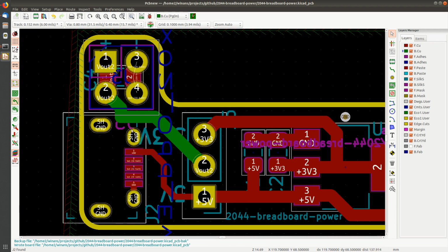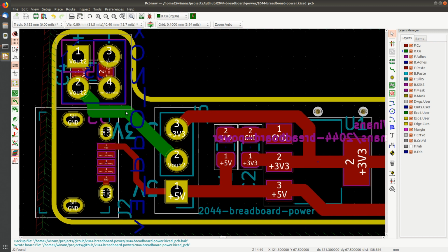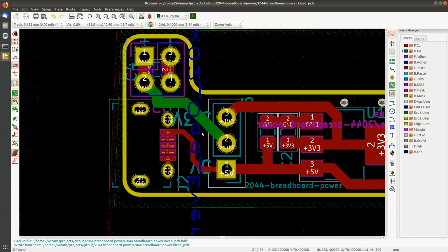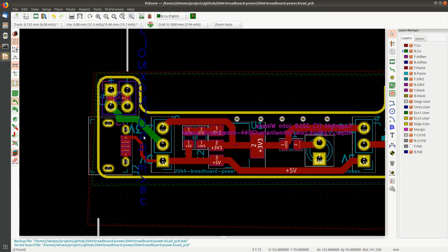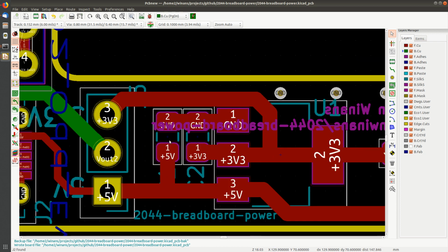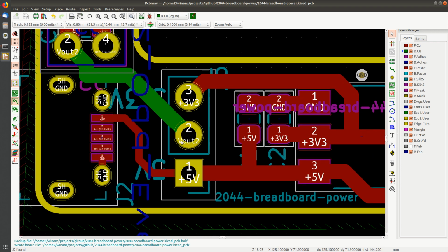That's okay though, because this pin's connecting the top copper as well as the bottom, as are both of these. So this on the top will be all copper up here. So it's good enough, especially for this simple design. Otherwise, you might need to put a lot of vias around here to keep everything satisfied if it's a high frequency design or something like that, because you do a lot of things differently in that case.